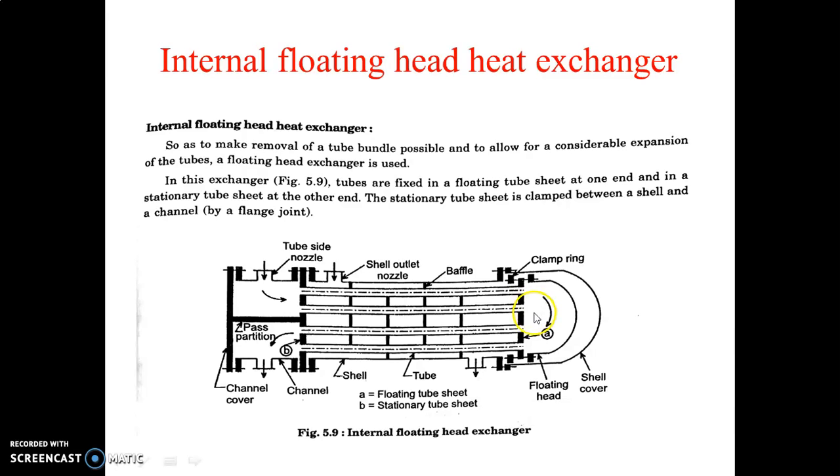The tube sheet along with the floating head is free to move, so that it can take account of the thermal expansion between shell and tube. So if thermal expansion takes place here, it will move freely. So it will account for the thermal expansion.